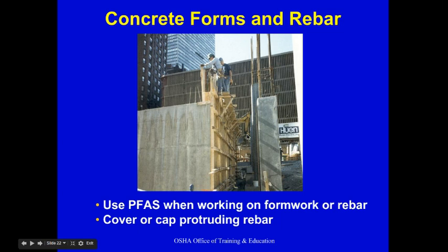A safety monitor is that last form of fall protection. So you know that you have the personal fall arrest systems, you have the guardrail system, you have a net, and your last option is to have a safety monitor. And that safety monitor is someone whose only job is to watch the workers. That's their only job. Because in some instances, although this one they could protect these workers with guardrail, in some instances in construction, it's not possible to provide a net, a personal fall arrest system, or guardrail. And in those instances, you have to have a safety monitor who just walks around and just checks the workers to make sure that they're safe.